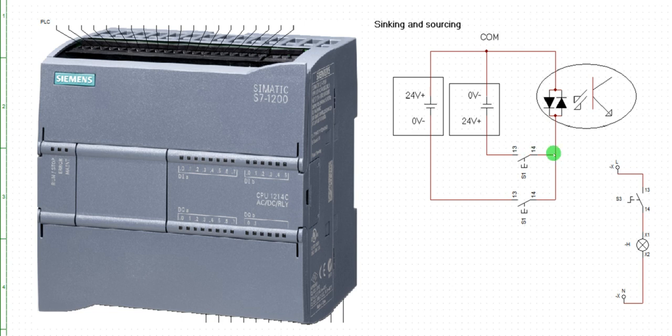All right. So because of that, I discovered that in some CPUs we have, look at this diode. This is reverse bias, this is forward bias. These two diodes are a way of polarizing that connection internally. That is how some of the CPUs accept both sinking and sourcing connections. So if this connection is carried out, this one is positive, passing through a switch to my CPU input card. Then this is negative, passing through a switch to that same input card. So this input card accepts these two connections.